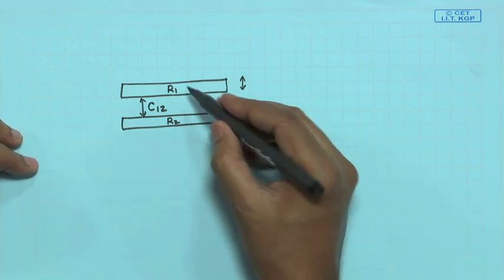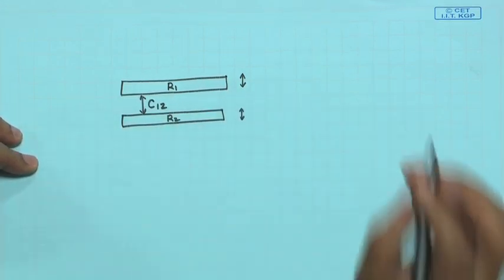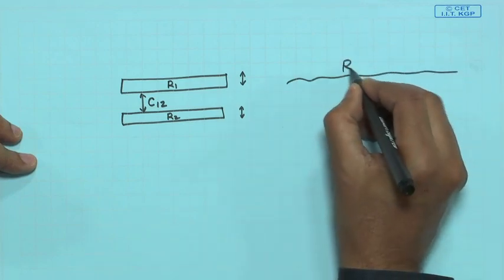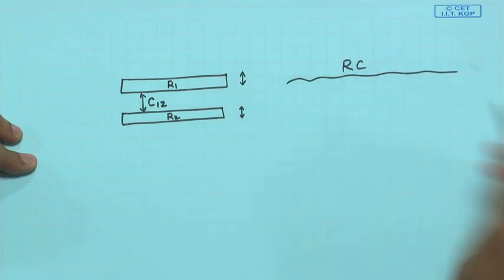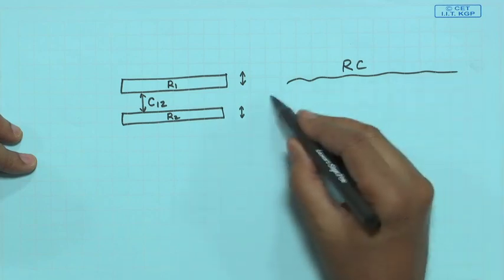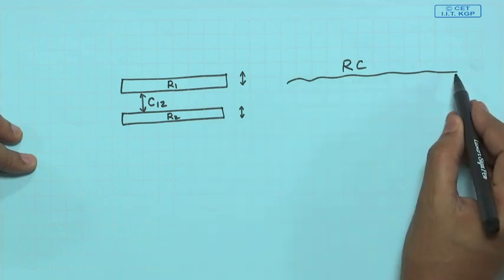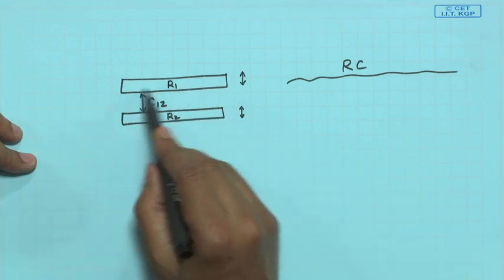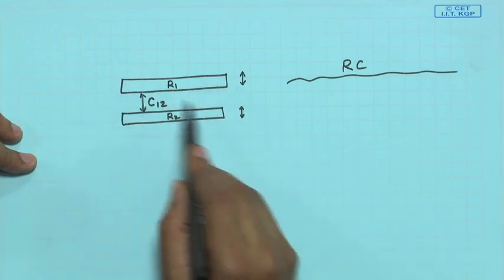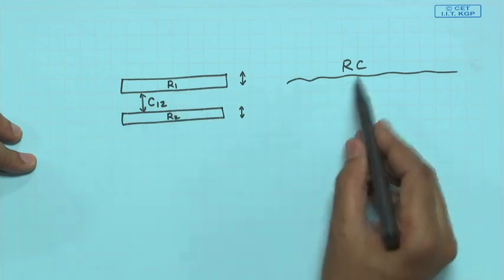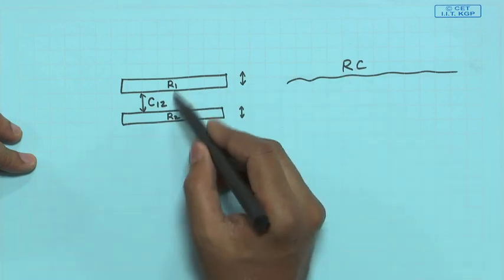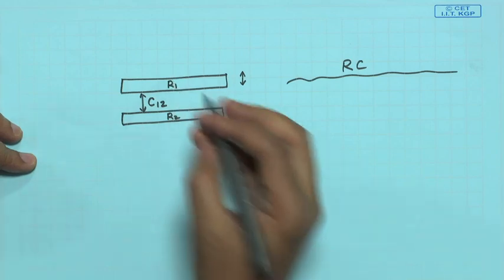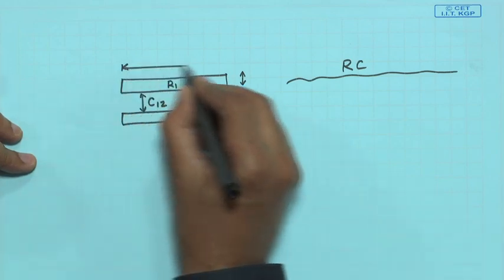running wires. So, basically, as I mentioned earlier, when you have a long transmission link, the RC delay comes into the picture, and there are some approximate ways to model these delays, like the Elmore delay model. Similarly, here also when some wires are laid out, there can be some RC delays, and these delays will be dependent upon the width of the wires, of course, the lengths.